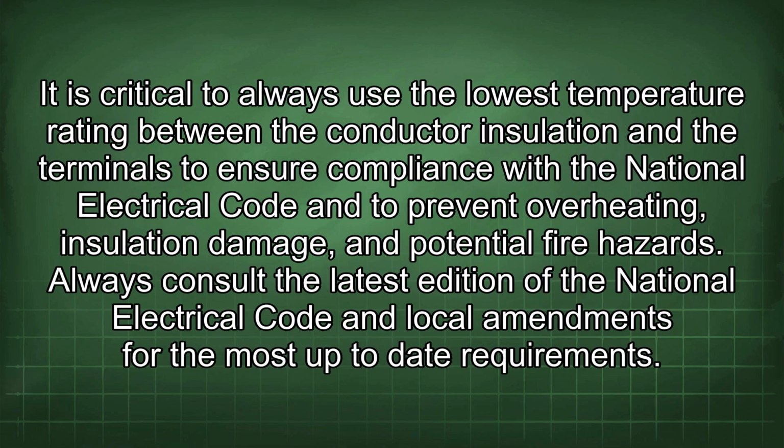It is critical to always use the lowest temperature rating between the conductor insulation and the terminals to ensure compliance with the National Electrical Code and to prevent overheating, insulation damage, and potential fire hazards. Always consult the latest edition of the National Electrical Code and local amendments for the most up-to-date requirements.